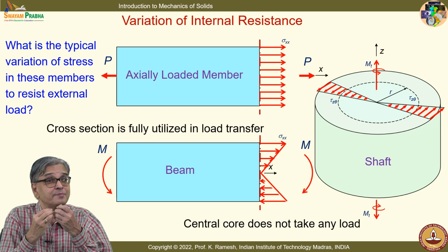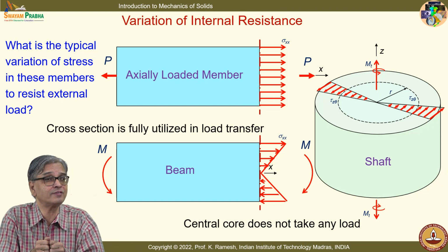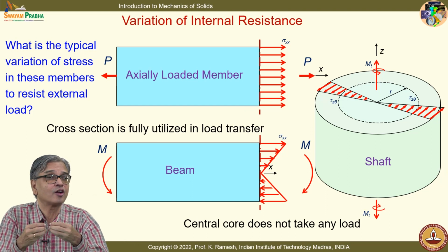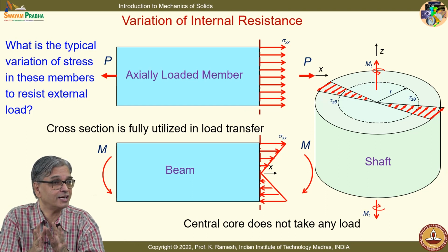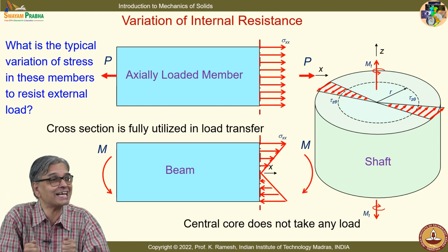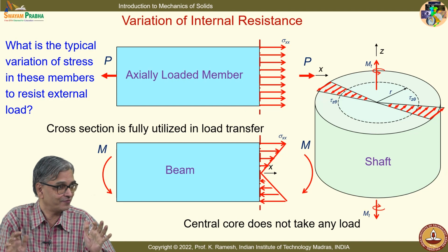So, the message here is, why did you develop a truss in such a manner? You utilize the material very well, because whatever material I put in, every part of the material contributes to load sharing. And you are also very clever, a transverse load is felt as axial loading. Fine.